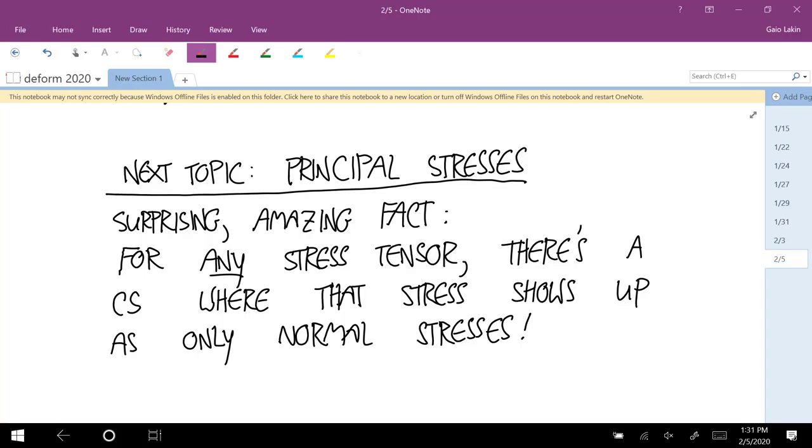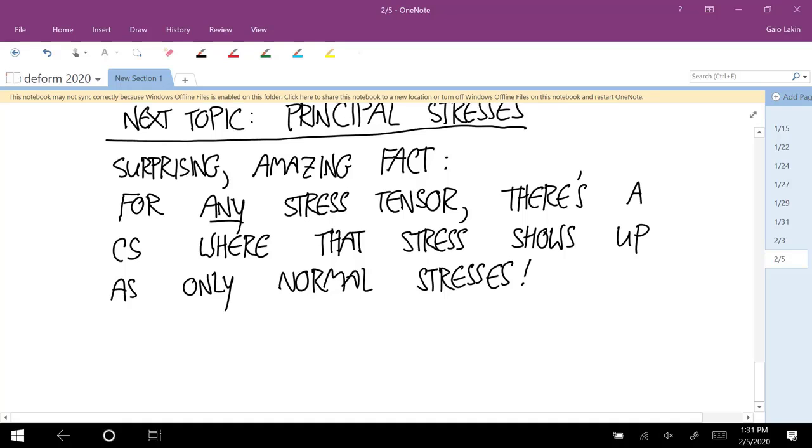It's a little surprising because you kind of have this feeling that shear stresses and normal stresses are fundamentally different things. The name of shear stress is because you sort of create those stresses by doing what scissors do to a material. You push down on one side and push up on the other side. But it turns out that the fact that it's a shear stress really has to do with what your coordinate system is. Okay, well, you have to give me that. It's pretty surprising. But whether it's useful is not clear yet.